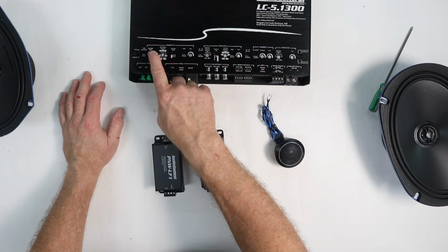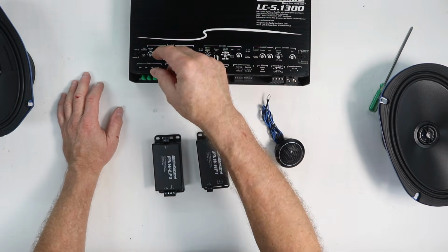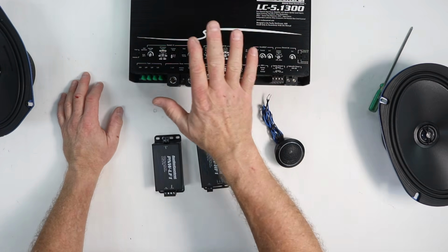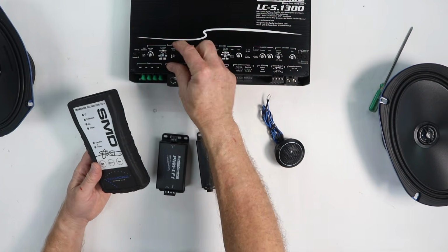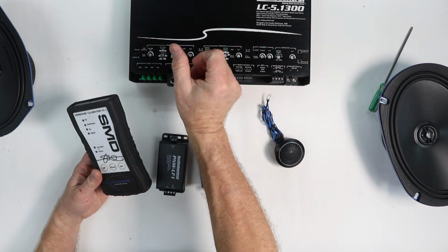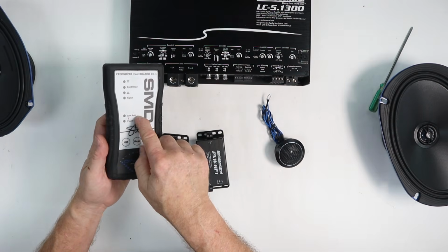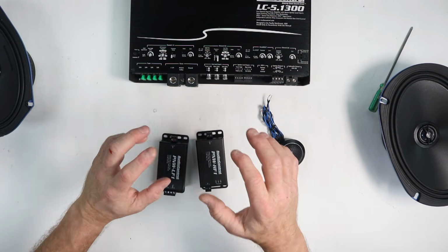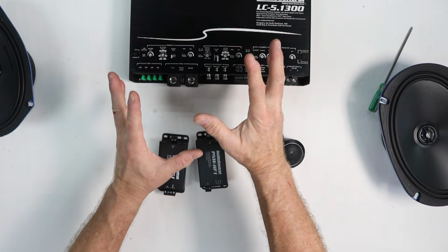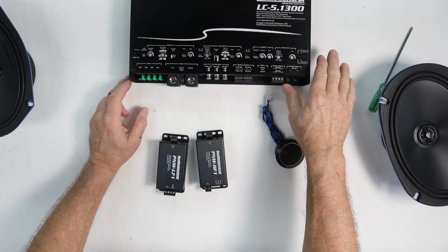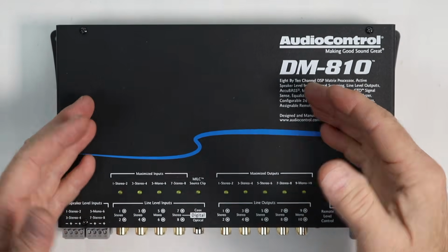When going active using dials like this, you can screw it up and get it wrong because it's a dial. Anytime I have to do this, I use the SMD CC1 crossover calibrator because there's no way for me to know where this gain pot is. This will tell me. A better way to do it, which is the most popular way right now, is with a DSP. Go full active, full crazy. Forget all of this nonsense of turning dials. We want this guy. DSP, that's right.